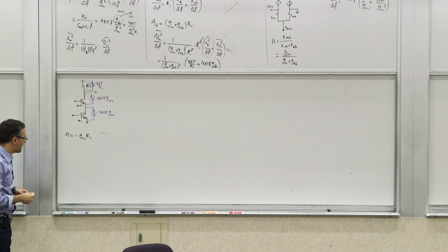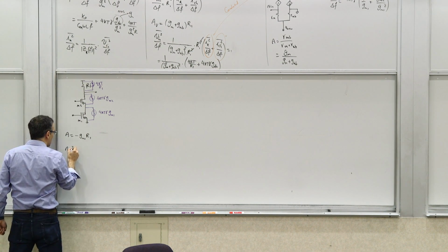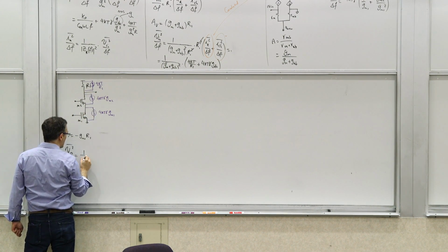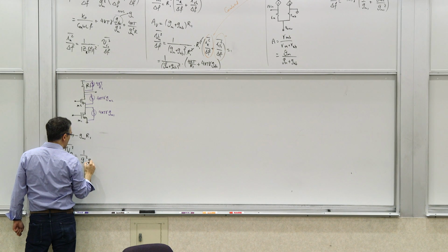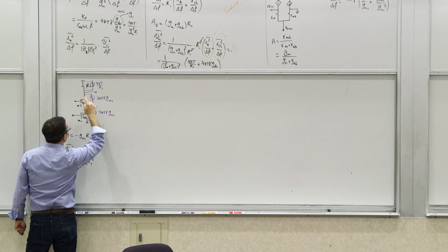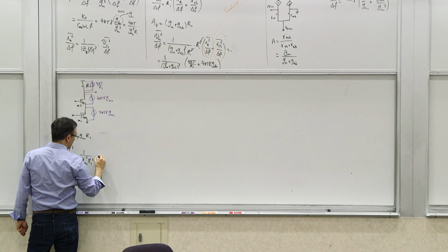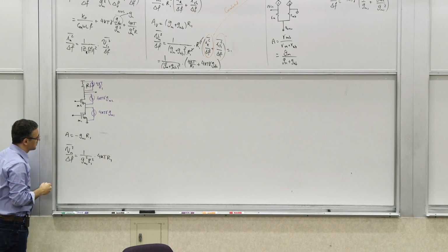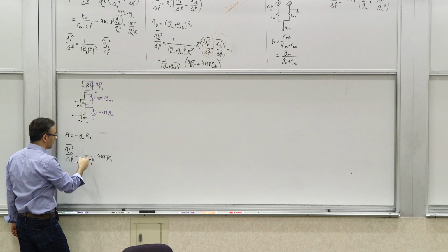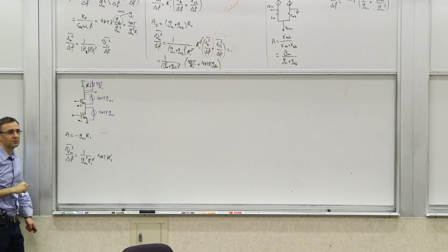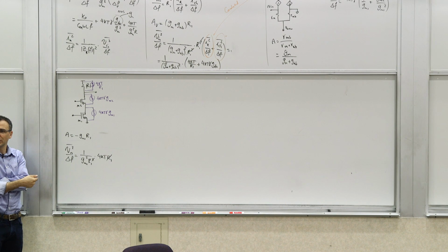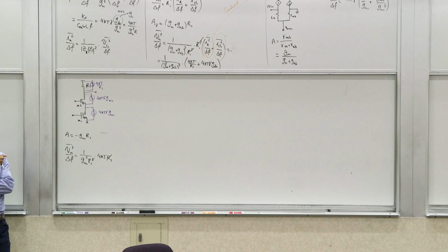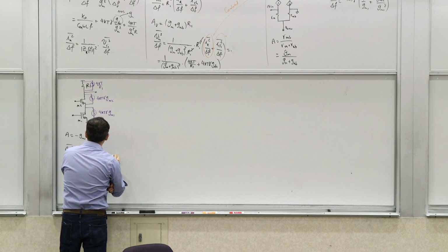So at the input, due to this resistor, I will have 1 over GM1 squared R1 squared times this, which would produce the voltage for KT R1. That's the contribution of this at the input. I'm reflecting them to the input, doing the same thing in one shot as opposed to two steps, so get used to that.